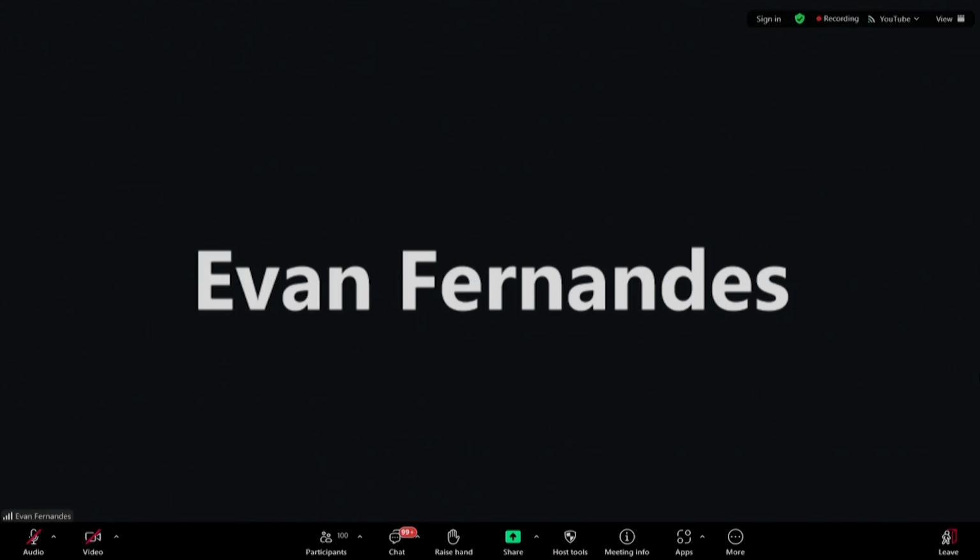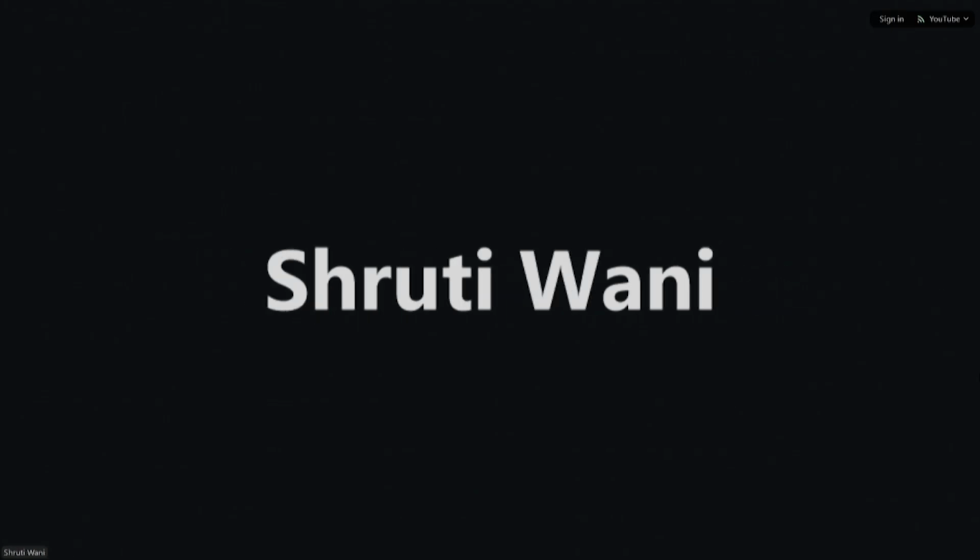When you copied the 50 folder into your 0 folder, did you clear out the whole thing? Like, are scalar 1 and scalar 2 still there? So in the 0 folder, I kept scalar 1 and scalar 2 as they are. I just copied T and U. T and U, right? Yes, sir.